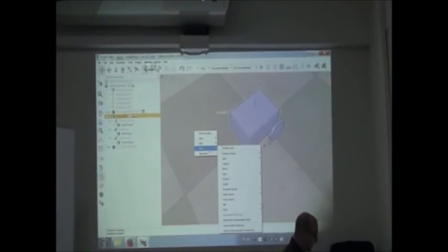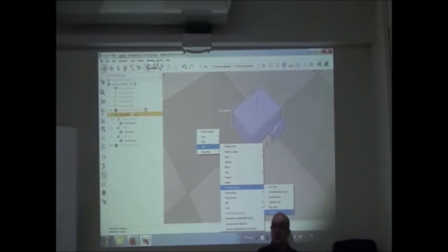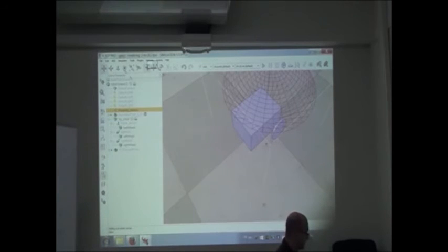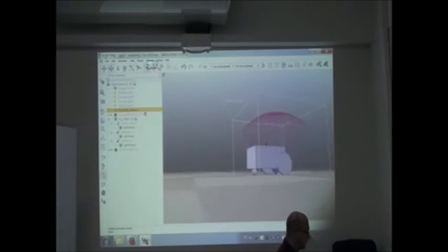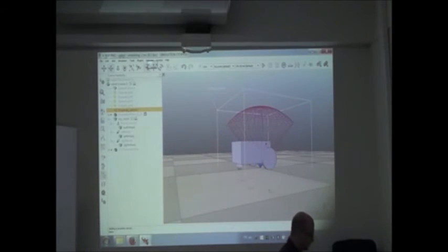With the right click, add proximity sensor. We want it to be a ray type proximity sensor because this is the sonar. Look, it did one, but it's not located at the proper place, and maybe it doesn't have the proper parameters. So let's put that in front of the robot here.